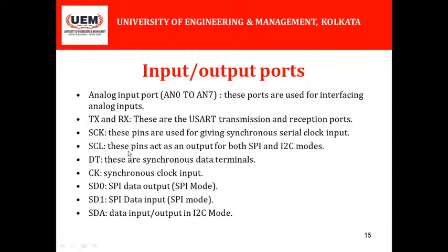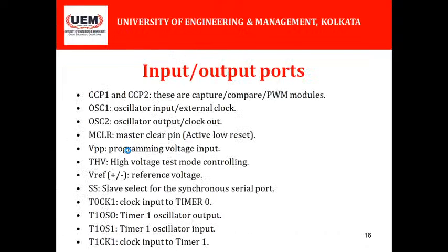DT stands for data terminal. It is synchronous in nature. CK stands for synchronous clock input. SDO stands for SPI data output. And SDI stands for serial peripheral interface data input. SDA is a pin which stands for serial data input and serial data output in I2C mode.